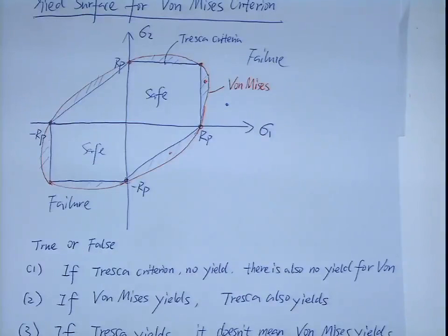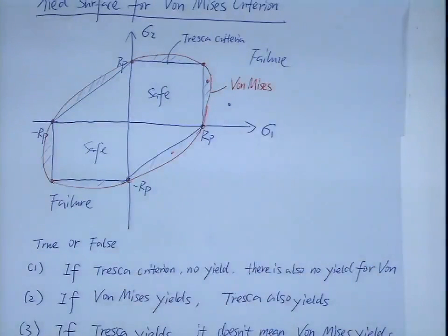So that raises some questions. Which one should I use in most of our engineering applications? Actually, there are not too many differences, so both are okay, I would say. But if you really push the boundary, then Tresca. But for most computational calculations, if you're using Abaqus, they much prefer this smooth version because that will reduce some convergence problems in your calculation.